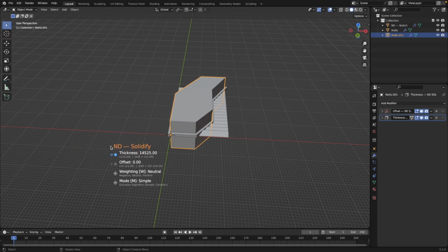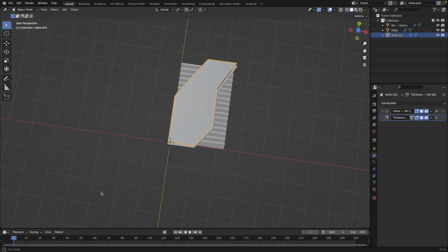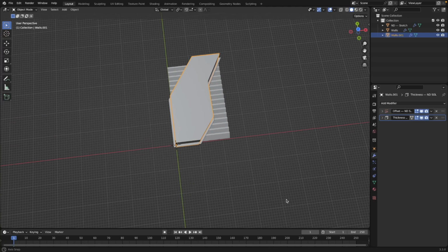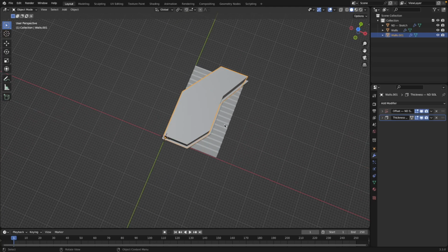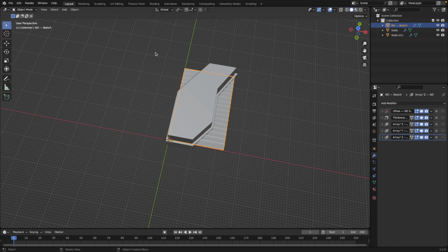Like the height here doesn't really matter, other than it just has to be taller than the vent that we're working with. And it's nice to make it a little extra, nice and chunky here so that we can really see it very well. So now this is the shape that we want to take. Wherever this intersects with these vents, though, that's what we want to keep. And where they don't intersect, we want to throw that away. So we use the intersection modifier to do that.